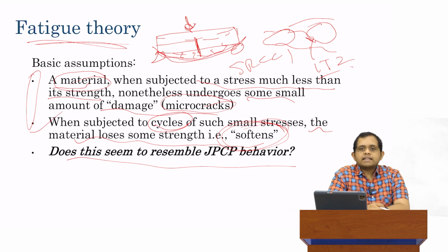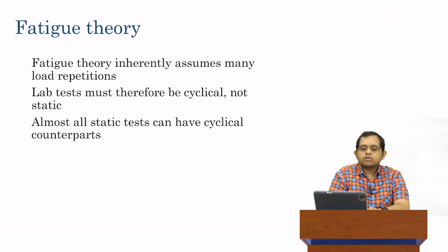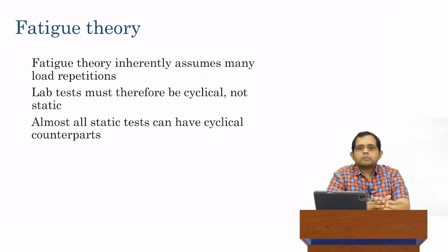So at least on that level, we can see that yes, it seems that the observed behavior of concrete beams, slabs, and thus JPCP, does indeed seem to match the assumptions behind fatigue theory. So that tells us we should probably use fatigue theory to analyze JPCP pavements. Okay, so, a couple of things about fatigue theory.